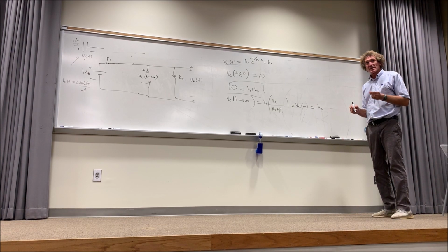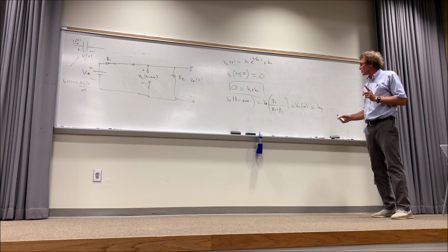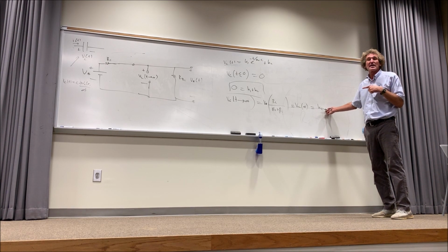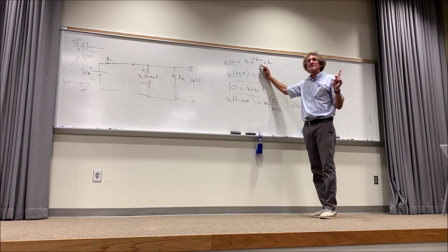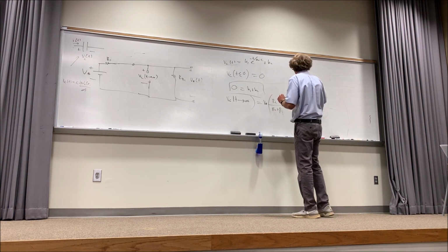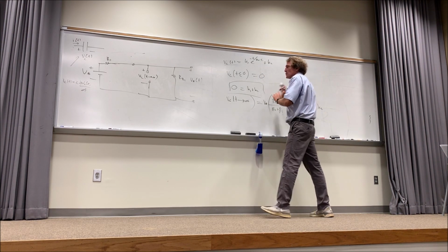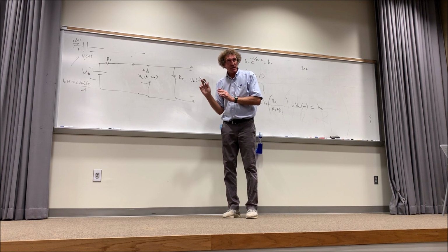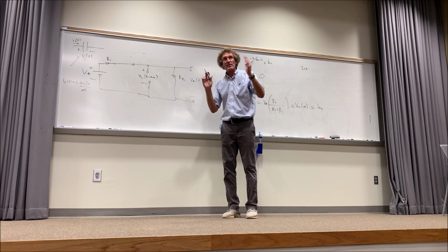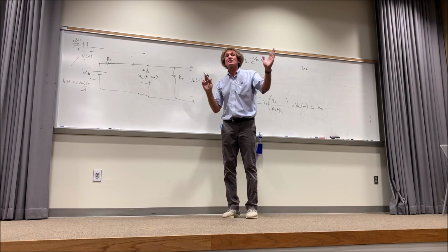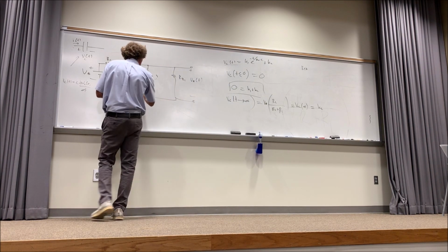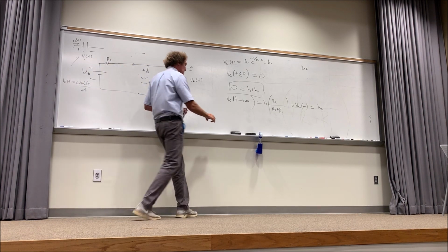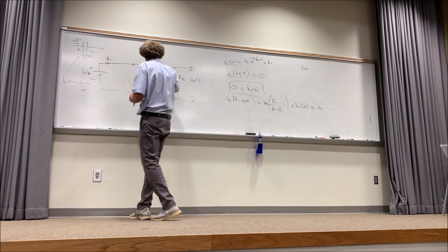Here, when you look at this, the next thing you need, we're almost there. Do you agree that this right here is just K2? We can find K1. Agree? But there's one thing we've got to get. That's R Thevenin. Now listen carefully. The way you find R Thevenin, you look at the circuit for t greater than 0, not for t less than 0. It's after the switch does its thing. Follow me? Then you find a Thevenin equivalent resistance right there.